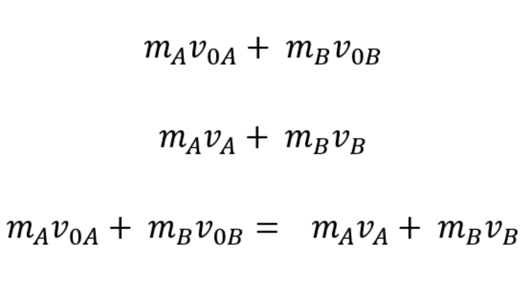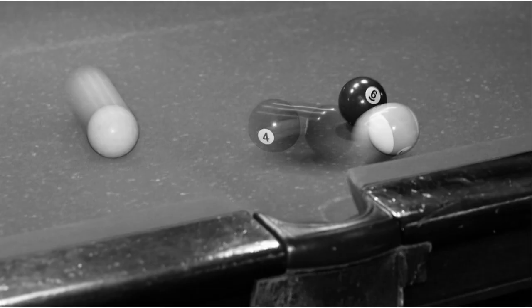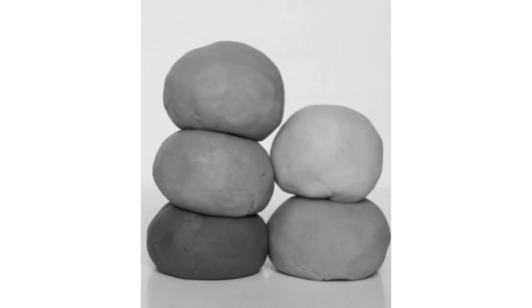We have to examine the effect of deformation, and subsequent restitution, of the colliding bodies during impact. The extent of restoration of the original shape immediately after collision depends on the elastic properties of the material. If the bodies are completely elastic, they will rebound and return to their original shape, like billiard balls. If, on the other hand, the bodies are completely plastic, they will stay permanently deformed and will travel together with the same velocity after collision, like two lumps of putty, you see.